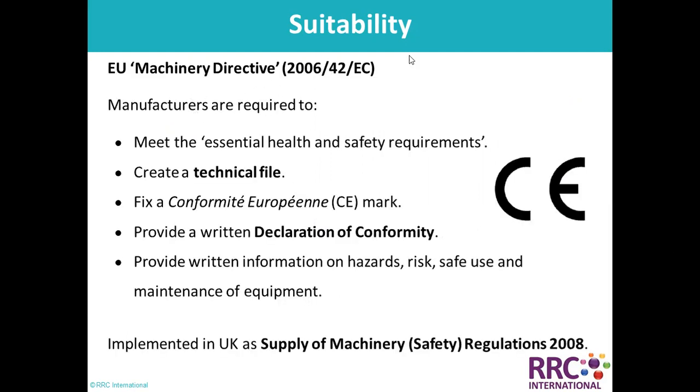So EU Machinery Directive 2006/42/EC, manufacturers are required to meet the essential health and safety requirements. That means they have to prepare kind of a technical file for each product, and fix a conformity mark like CE mark. Provide a written declaration of conformity that this product will not be harmful for intended use. Provide written information on hazards, risks, safe use, and maintenance of equipment.